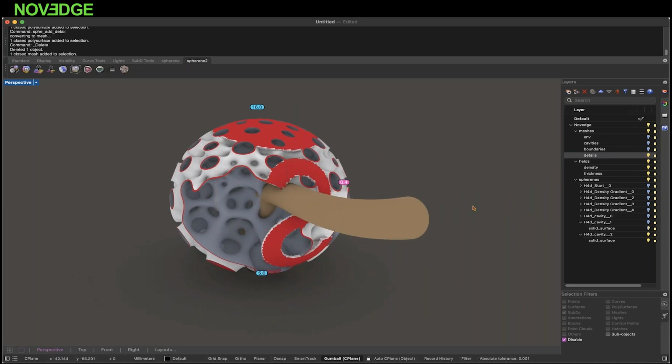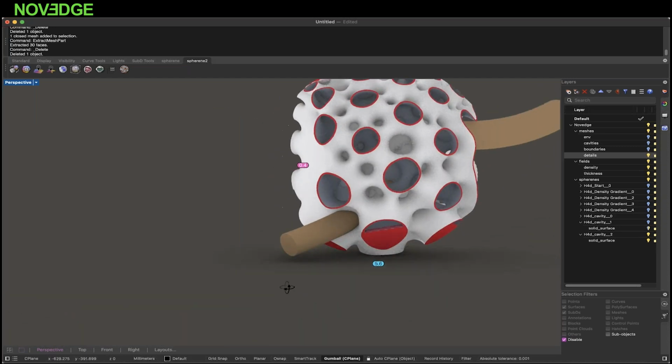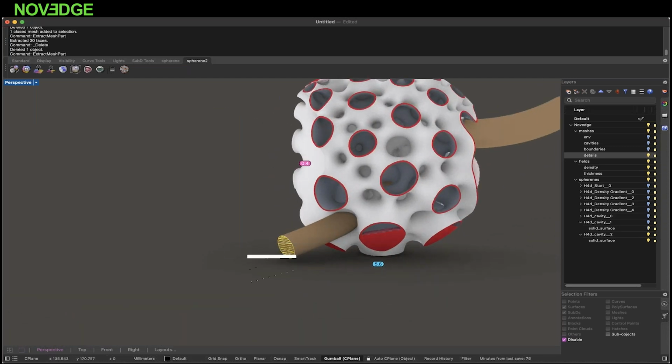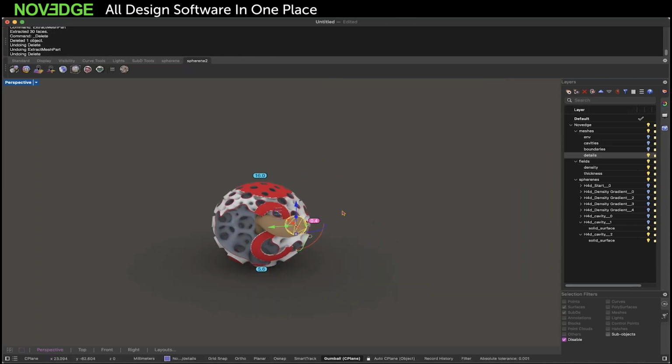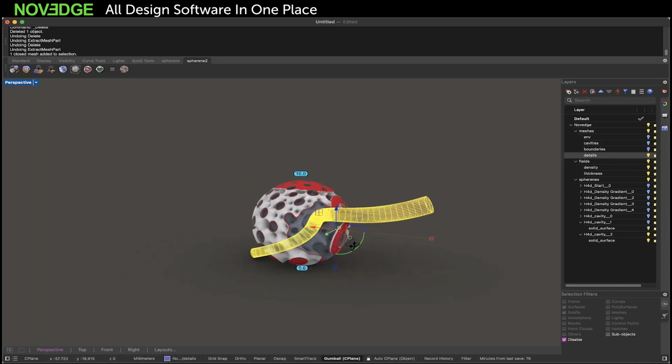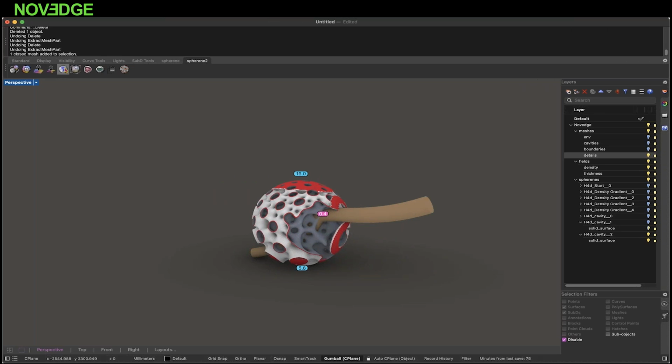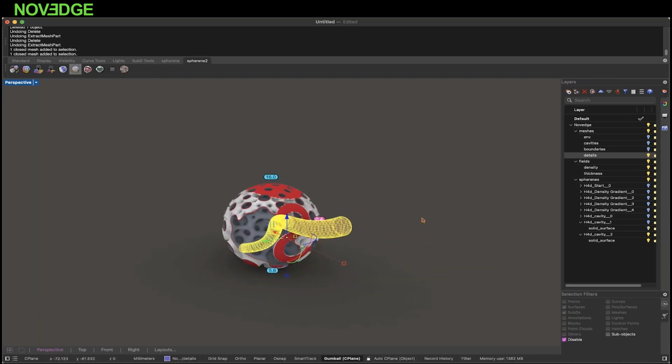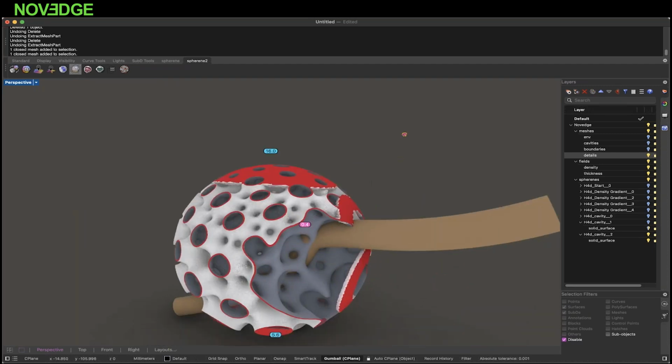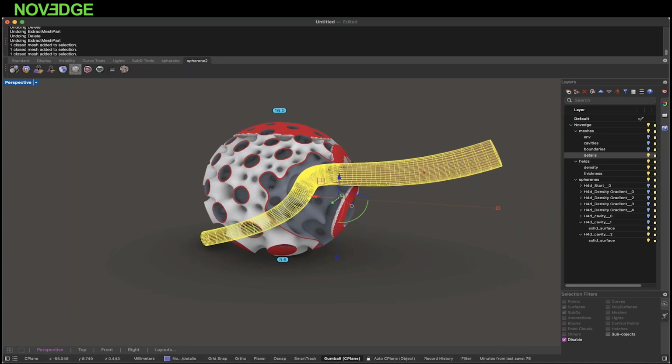And let's extract the mesh part here. Delete that one. So details can only be, no, that is wrong. We need it closed. That is something else. So what I wanted to say is boundary objects can only be open meshes or open objects, while details can only be closed objects. So I almost made that error myself now. So this is a detail.